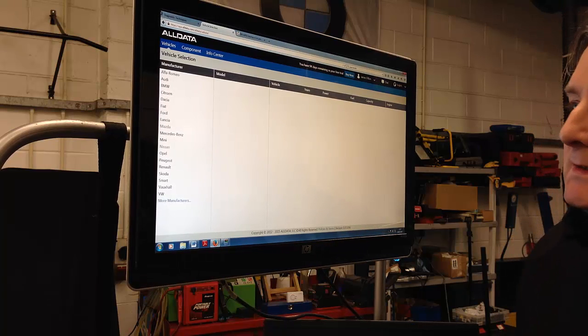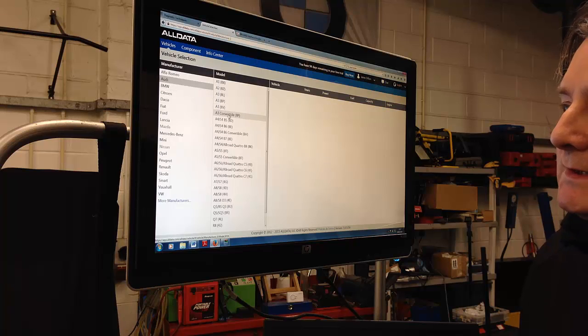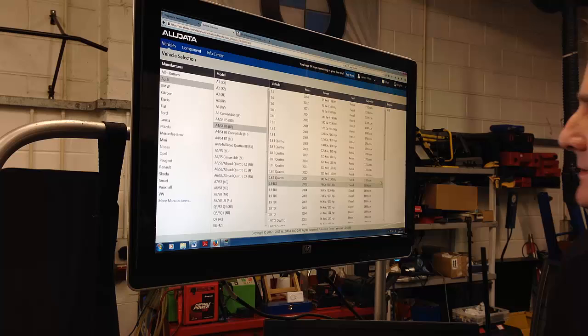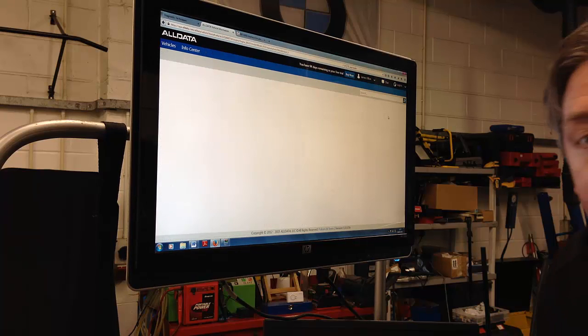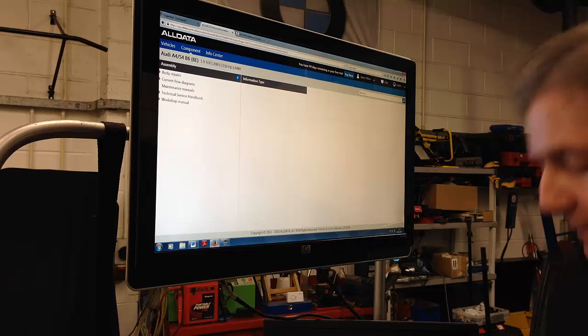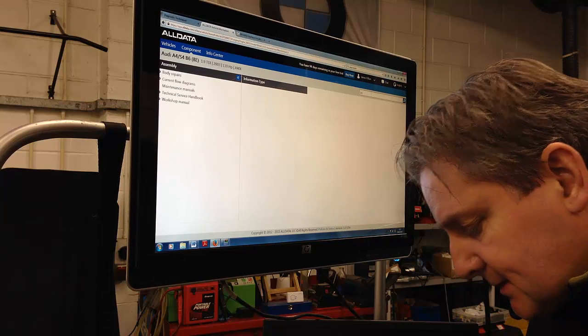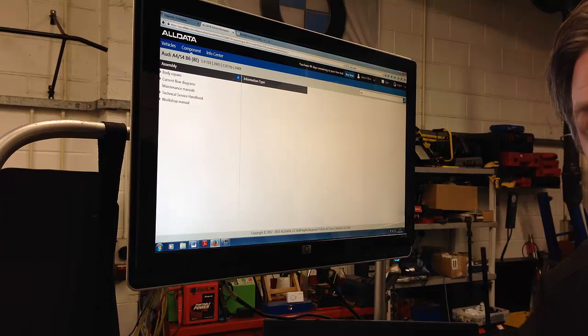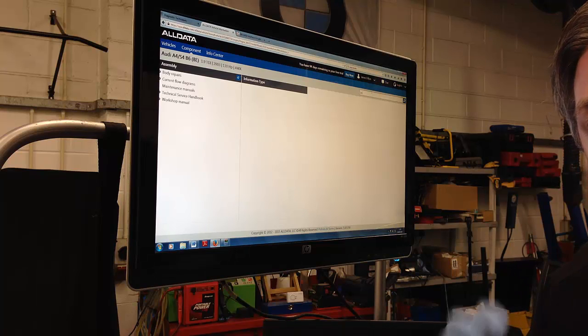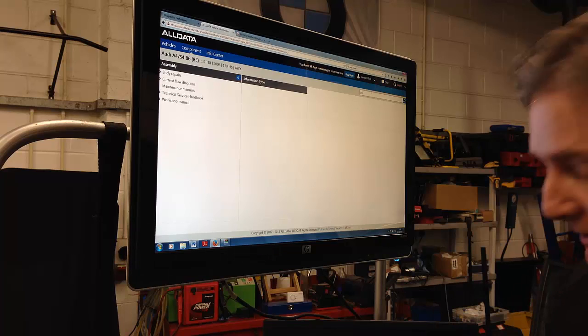Okay, so here we are at the test data, and we're going to take a look now at this Audi A4, try and get some diagrams up. Based on the data that we've got from the vehicle, we're going to look at a 2003 AWX engined 2-litre PD A4, so we want current flow diagrams. We're going to take a look at power, so based on the fault codes that we got, we're going to go power distribution, steering column control and or central convenience unit. We're looking for the data connection really between those things.